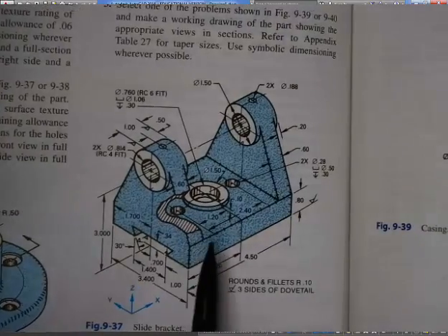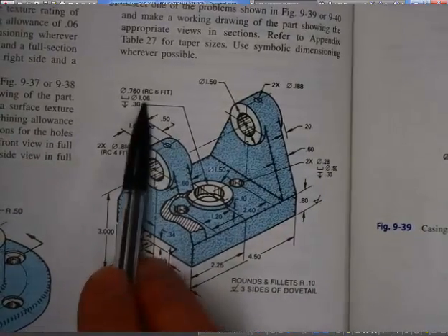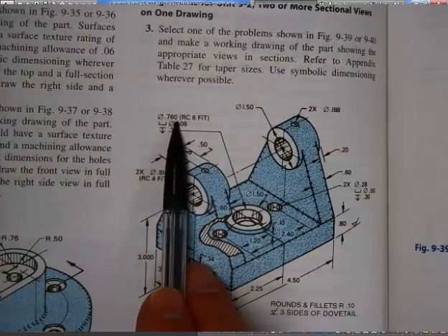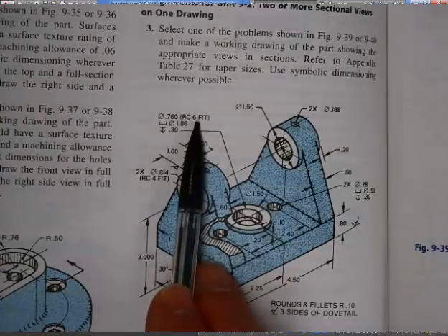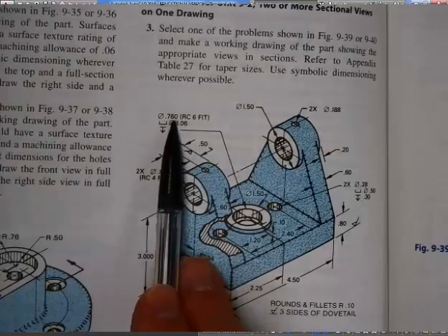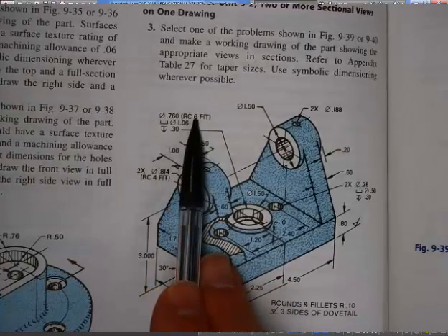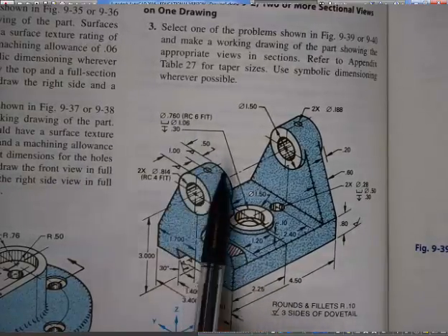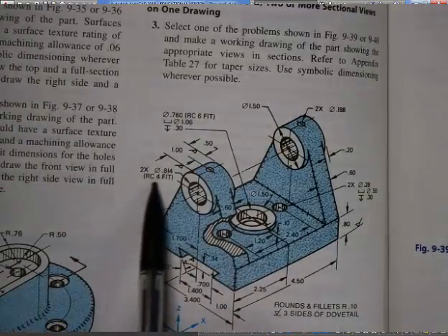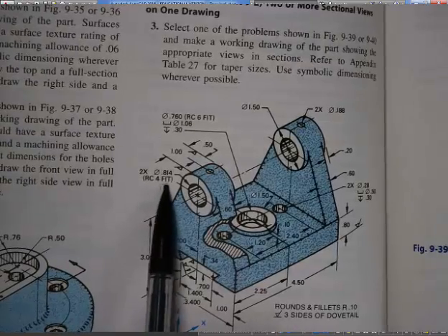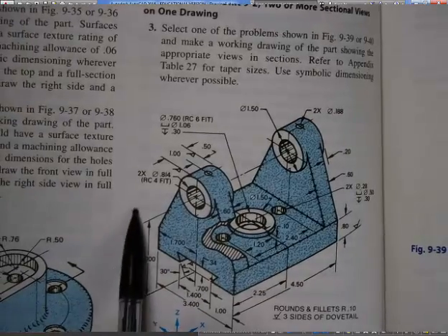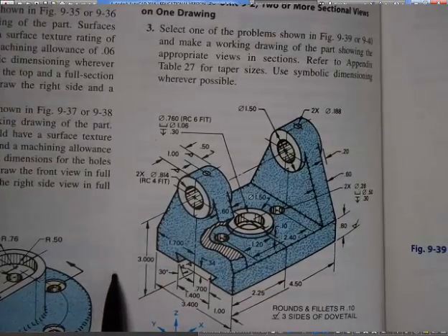Then on top of that, you've got some fit values here. So this one has a hole with a diameter of 0.76 that has an RC6 fit. So again, we know on holes that this value is the lower number. So 0.7600, go look it up and see what the hole tolerance is to find the upper value. And then again, your counterbore and your depth, same thing here. So this one cuts all the way through, so there's not a counterbore and there's not a depth, but you're going to look that up as well and show them as limits like we've been doing.